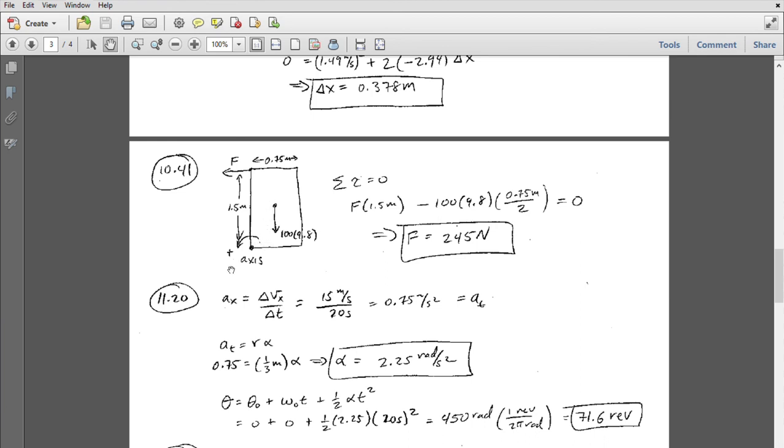But if we're calculating our torques with respect to the axis shown here, the part about which it's going to tip, we don't need to include that torque. There is no torque due to the force that's being applied right at the location of the axis. So the important forces are the one we're applying, which we'll call magnitude F, and its moment arm is 1.5 meters. If you go back and look at the problem statement, that's the height of the refrigerator.